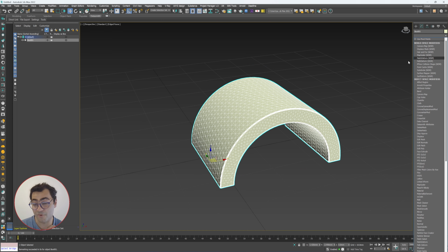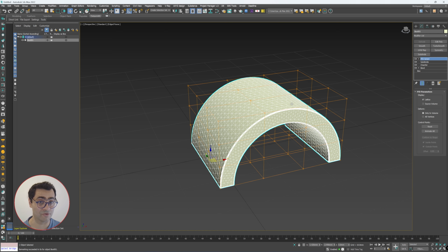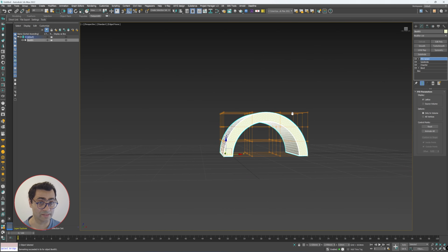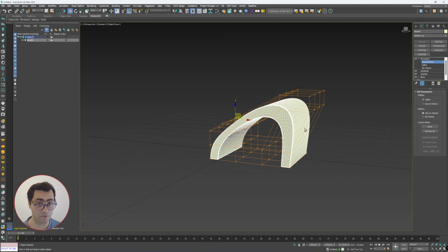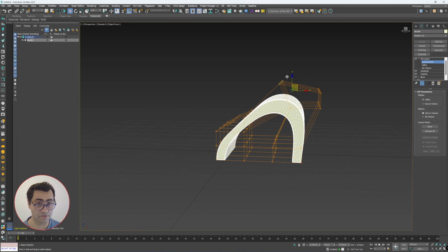The other most important one that you can probably be using quite a bit, modifier wise, is the FFD modifier. So we got 5 different FFDs here. Just basics of it is literally you can just do like a 4x4 one, like so, and then you can activate the control points like so, and then you can select the control points, and then you can move around some of them to create some really controlled structures, which is quite helpful.